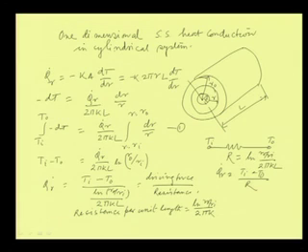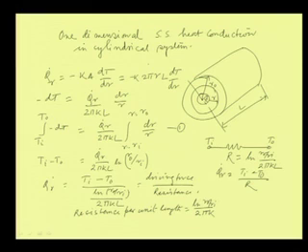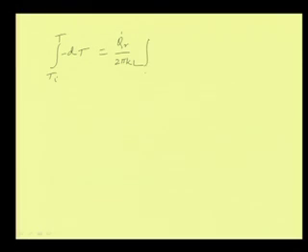In equation 1, if we change the integral limit, like if I write from T I to T, in place of T O, any temperature T, and here it is minus dT will be equal to, as it is written, Q dot R by twice pi k L, and then integral of dr by R, where R goes from R I to R.